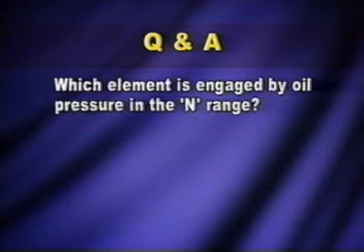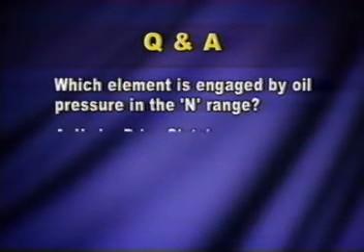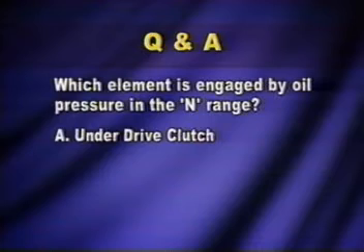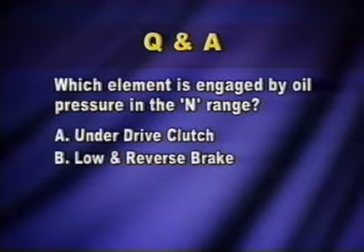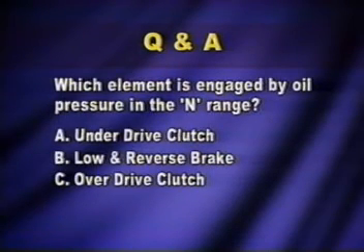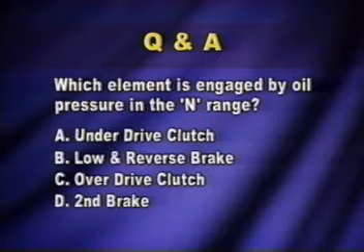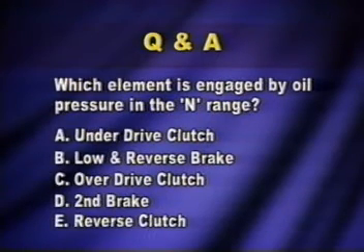Which element is engaged by oil pressure in the N range? A. Underdrive clutch. B. Low and reverse brake. C. Overdrive clutch. D. Second brake. E. Reverse clutch. The answer is B. Low and reverse brake.